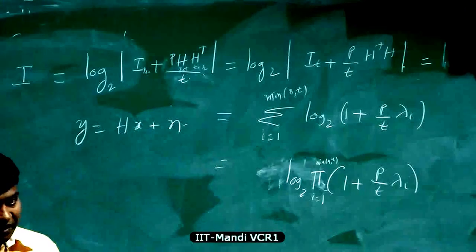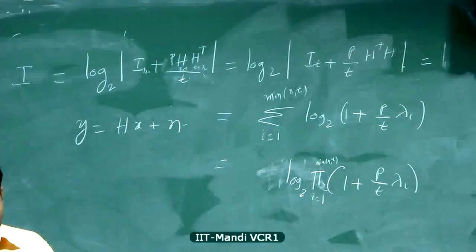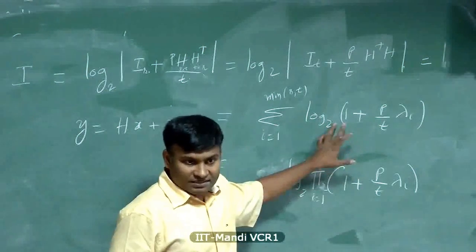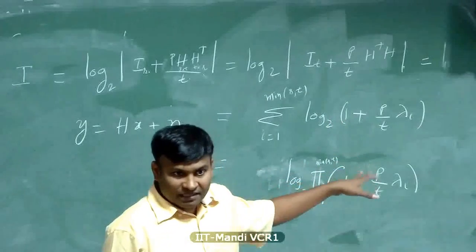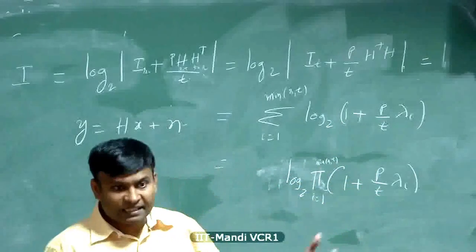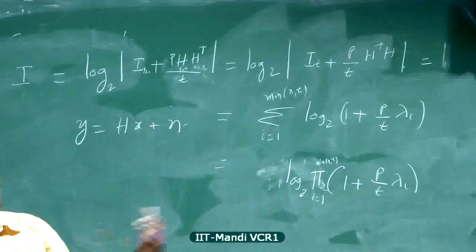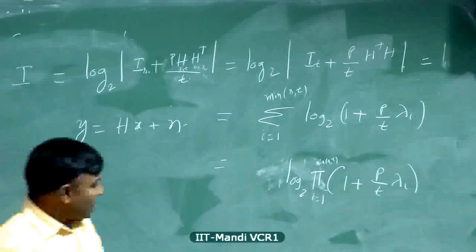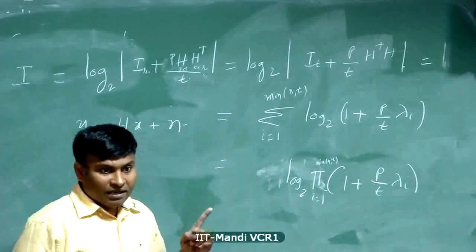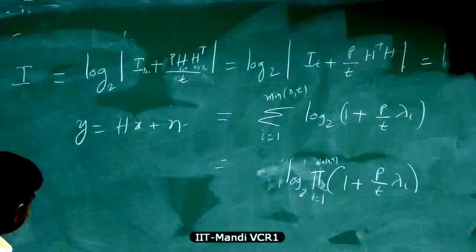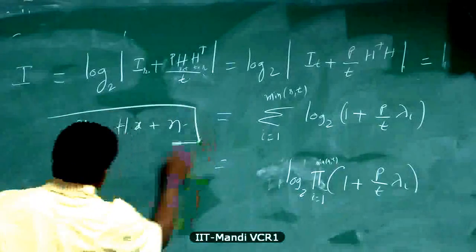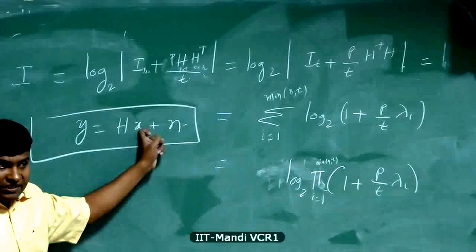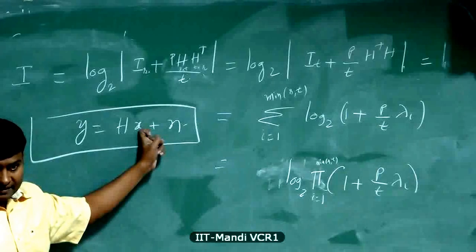Well, it turns out that something as simple as an MMSE receiver will not give you this capacity, but something close to this. There is a gap, right? An acceptable gap, and that gap can be bridged by using a few more receive antennas than transmit, because the MMSE receiver gives you a higher diversity gain. Right? And there is another receiver, what is called a maximum likelihood receiver, that works with this model, that jointly detects the modulation alphabets contained in the vector x.